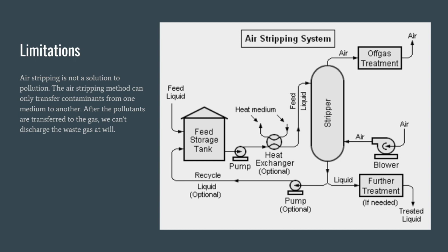Active carbon is simple, but it does not destroy the contaminant substance, and may result in potential disposal cost. Thermal oxidation destroys the contaminant, but is more complex during the process.